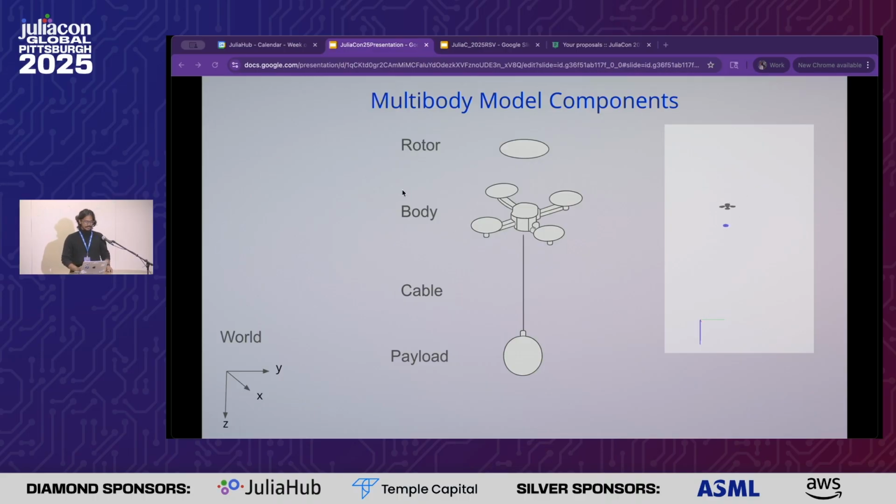So the whole system is comprised of four components: a rigid frame, a cable with n links (3 for this demonstration), and a payload that all lay inside the world frame. They're all easy to understand and define independently as components. To assemble the cooperative system, you just have to connect the frame of one component to the other. And as is evident from the simulation results on the right, it makes thinking about the control problem much easier.